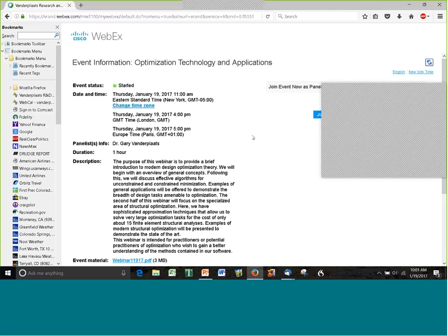out in the market. One is ANSYS, where we have an interface that lets you run Genesis along with the ANSYS solver for nonlinear analysis. And the other one is with LS-DYNA. So you should be able to do topology optimization coupled with a nonlinear LS-DYNA analysis.